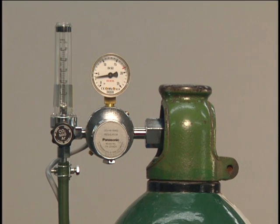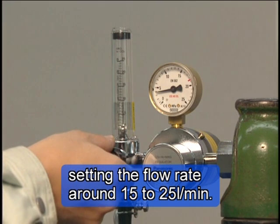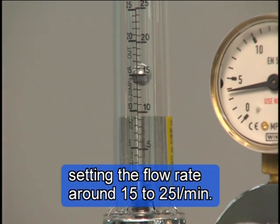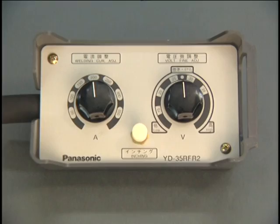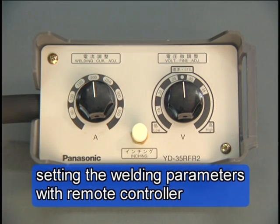The shield gas flow is adjusted to 15 to 25 liters per minute by the gas regulator. This gas should be without moisture per the JIS specification. Welding amperage and arc voltage is set by the remote control.